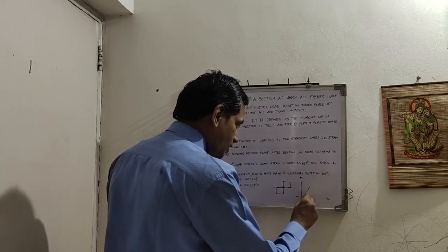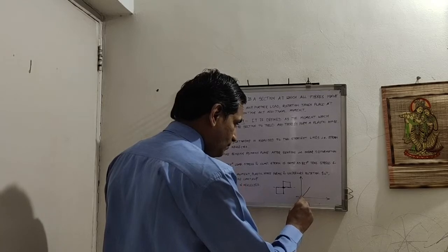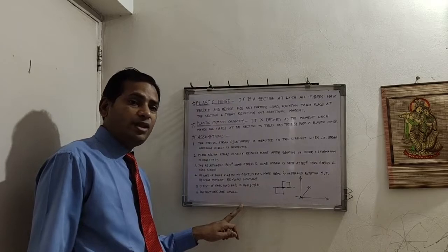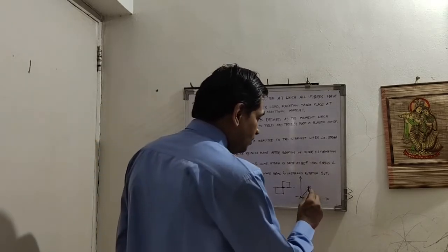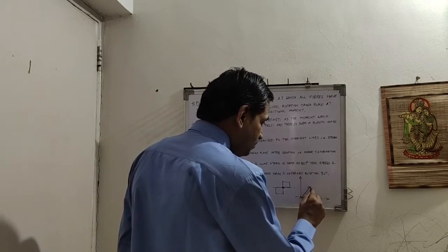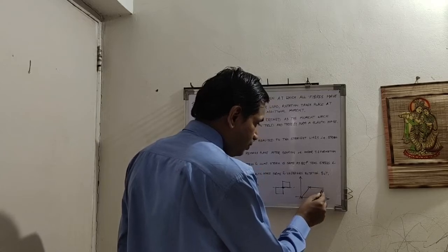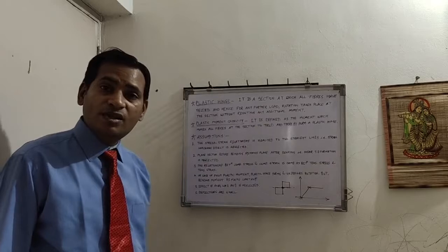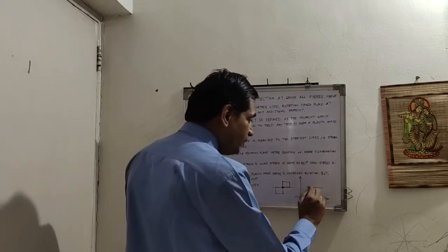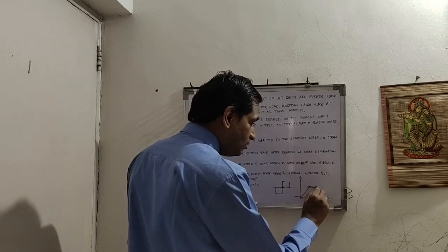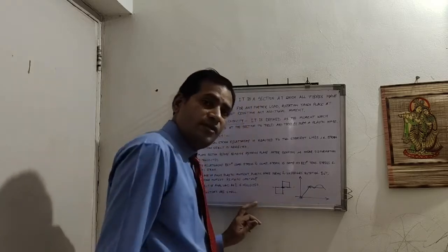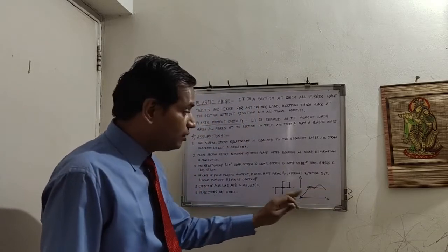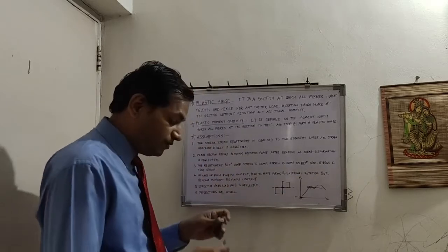Up to the yielding point, that is point C, this is one straight line, and whatever is the behavior of the material beyond point C, that is beyond the lower yield point, it is assumed as a horizontal straight line. So these are two straight lines. So instead of behavior something like this, we have idealized this stress strain behavior as two straight lines. This is our first assumption.